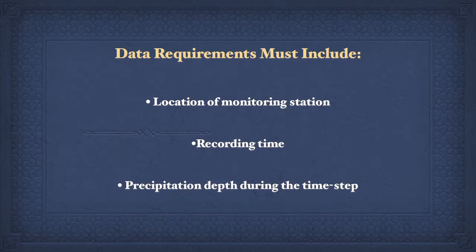Collect daily historical rainfall data from a consistent source whenever possible. If data must be combined from multiple monitoring stations, interpolate or average rainfall data from 3 or more stations around the site to even out any discrepancies with the primary station.